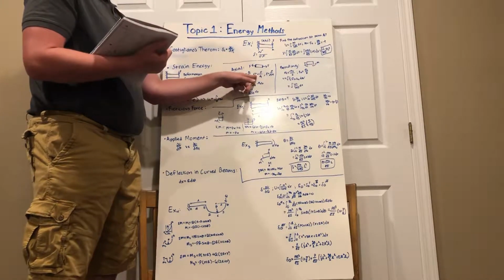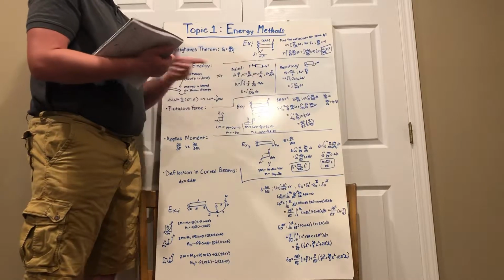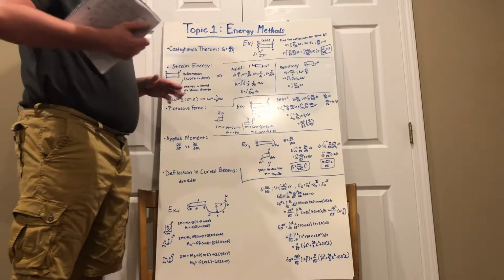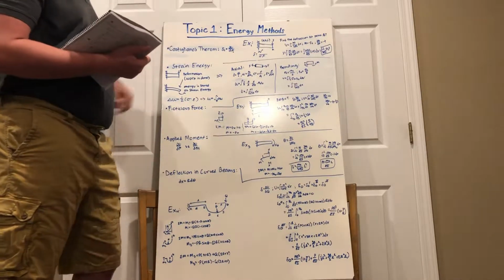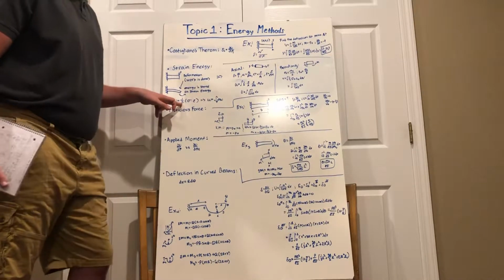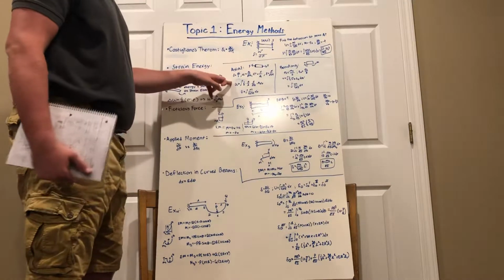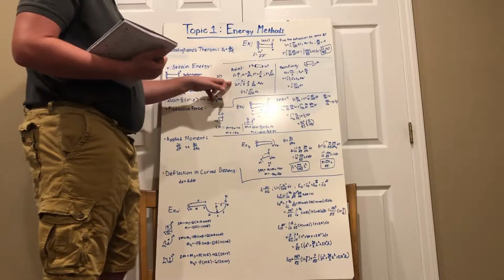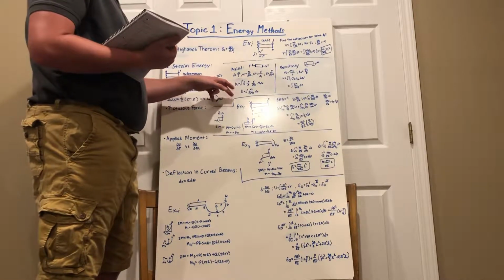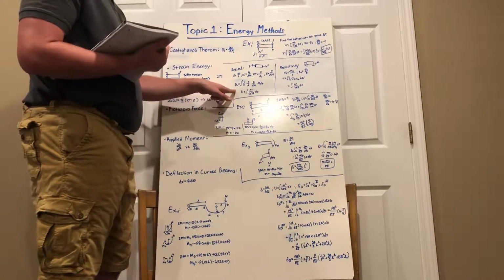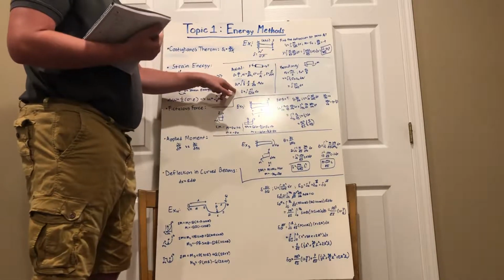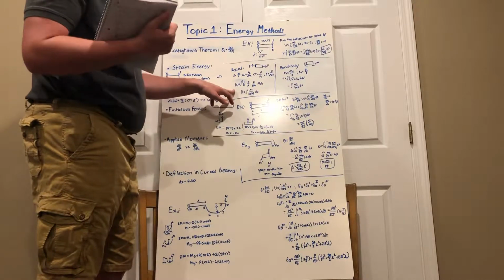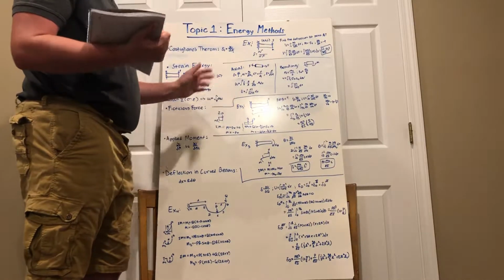Delta, or your sigma, which is going to be your stress, is going to be force over area, and your epsilon is going to be force over E times A. All right? Now let's plug all these back into this original delta W equation. What do we get? We get 1/2 times F over A times F over EA times A dx. Now what does that reduce to? I know this is kind of a change of variables, but bear with me. It's going to boil down to U is the integral of F squared over 2EA dx, right?